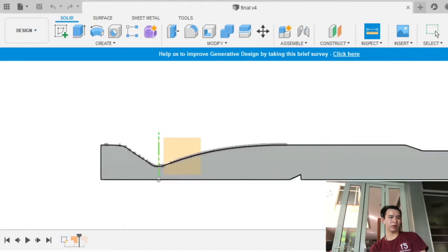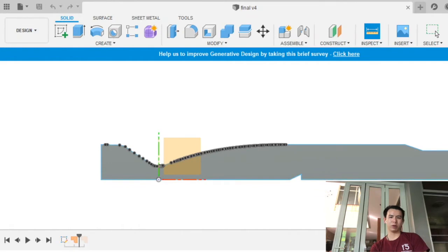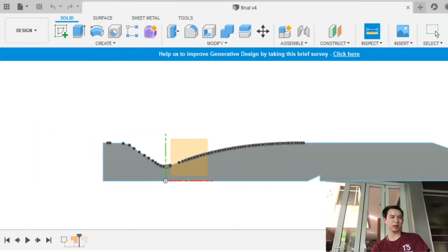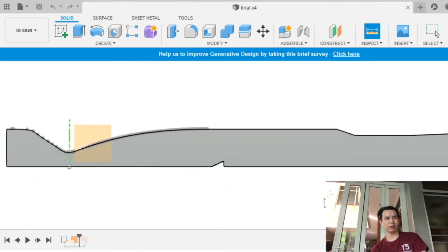Start off with drawing the inlet and the nozzle. The nozzle contour is produced by MATLAB from George the Engineer with the modified code from LAM, which gave me the .csv file of coordinates, so that I can just import those coordinates right into Fusion 360. It creates this curve for me, which is the perfect contour to prevent any undesired shock wave.